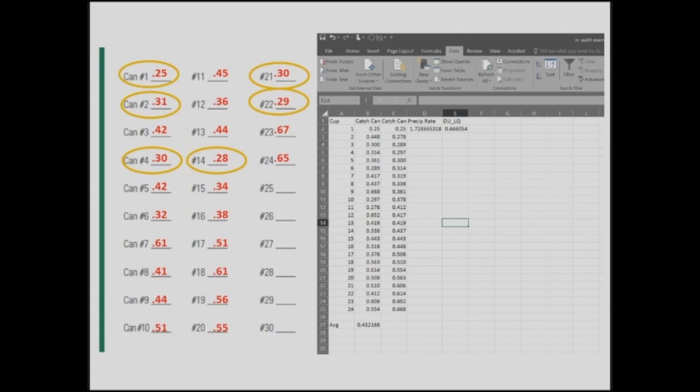It's always dangerous to do math on the fly. Let's see here. So 1.72 inches per hour. That was our precip rate. And Chrissy's going to talk about how we define the amount of water we want to put out. If it's something like a pesticide application, the label might dictate it. But in other cases, we want to try to target what the plant needs.